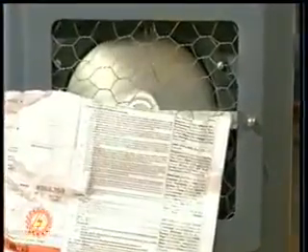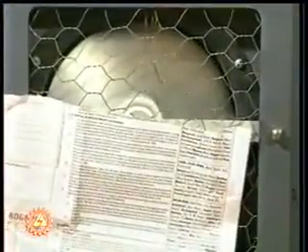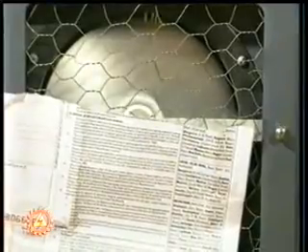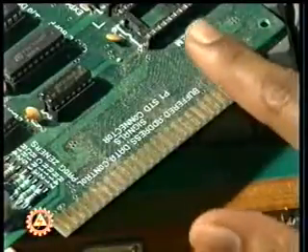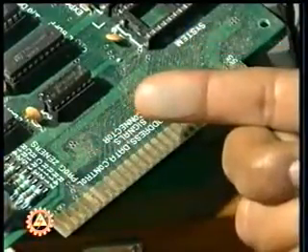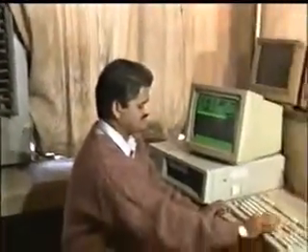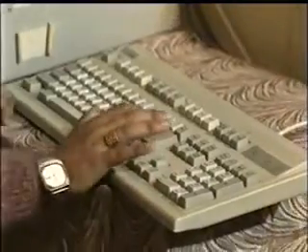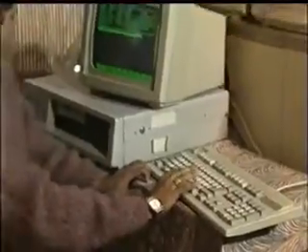High temperature may be caused by a blocked air unit in the equipment. Dust deposition on PCB fingers may make the contacts unreliable. Excessive humidity due to cooling equipment may again create contact problems and surface leakage problems.